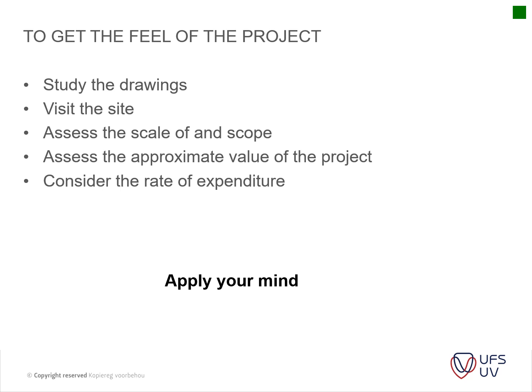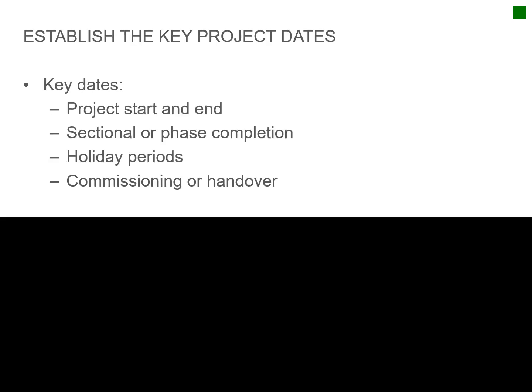Okay, the main thing is to get the feel of the project. You have to study the drawings. You have to visit the site. You have to assess the scale and scope of the project. You have to assess the approximate value of the project, and you have to consider the rate of expenditure, and you have to apply your mind. That's the main thing, is common sense. It becomes common sense in certain areas as you get more experience in planning a project.